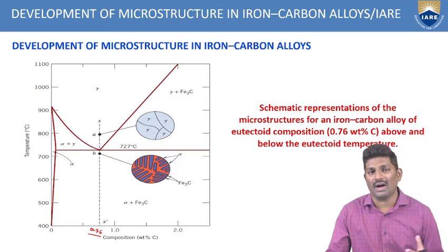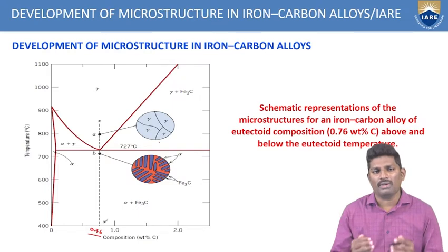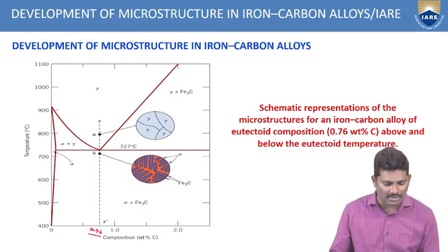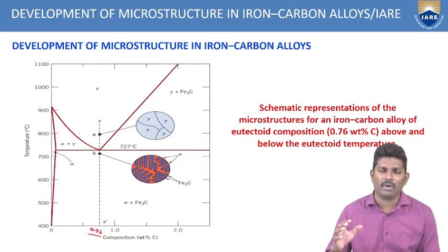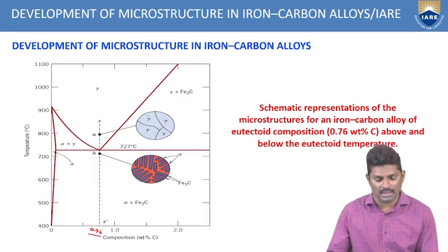Okay, you have austenite percentage very, very high at this point. Now, when you come down, that means when you reduce the temperature, at some point, so point A is approximately around 800 degrees centigrade. At that point, you have a lot of austenite. So you have all the gamma microstructure related to this at this point.